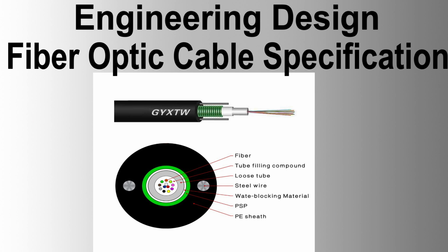Termination. Responsibilities. The contractor is responsible for termination testing up to patch panels, providing 10 meters of slack where the FOC has to be terminated. Termination process. Use fusion splicing for the pigtails and bare fibers from the FOC, organizing and securing the loose fiber well in the splice tray. Route each subsequent section end inside a splicing chamber, leave it as a loop of cable, seal, and secure it with sufficient excess cable for splicing at joint locations along the pipeline route. Ensure sufficient length at cable ends to allow termination within the facility, coiled and protected with ends identified and sealed.